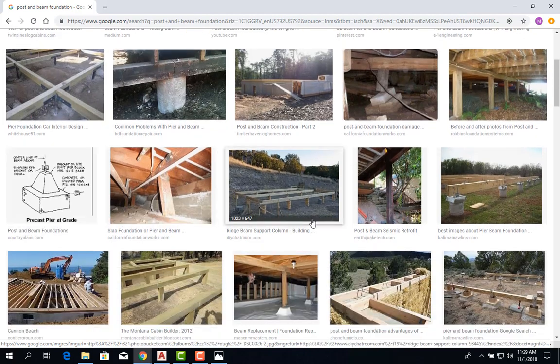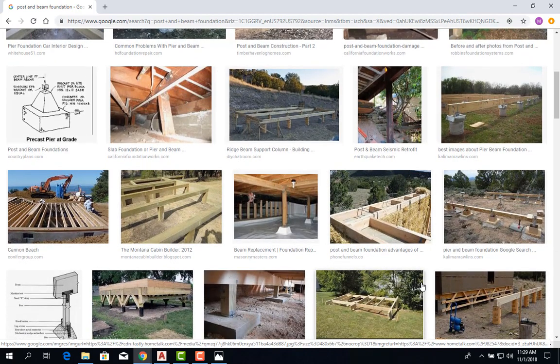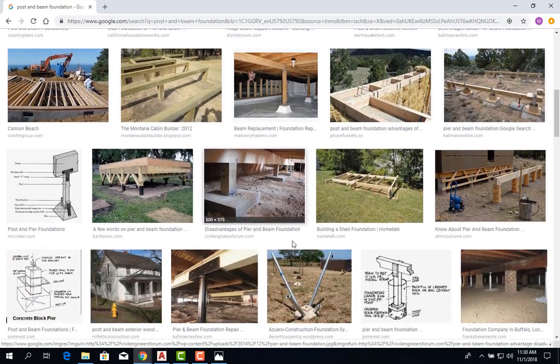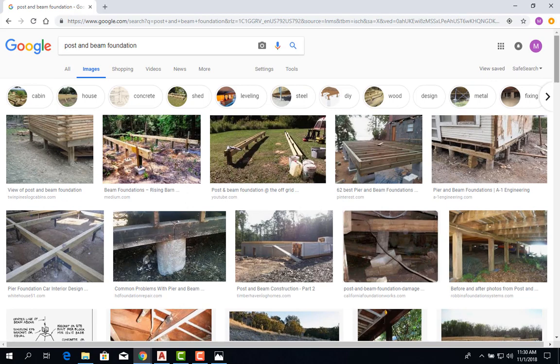Okay. So again, the foundation is going to depend on the area, on the soil that you might have. So don't think it's just one size fits all. You need to know the soil, you need to know the freeze line, you need to know what you're going to design, so you provide the adequate foundation. Okay. I think I went over. I didn't want to spend too much time, so I apologize for that.